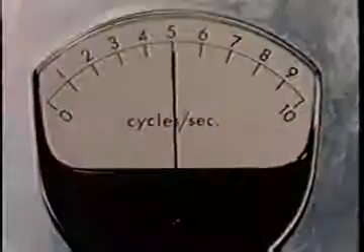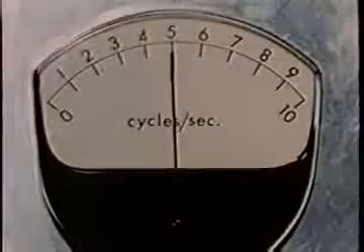In order to find the frequency response of amplification, we put in sinusoidal disturbances which we can control. We start the wave maker oscillating at 5 cycles per second. At 0 airspeed the waves damp as they travel away from the wave maker. With the tunnel running, but below critical airspeed, we don't notice much change in wave damping. As we increase the airspeed and pass critical speed, we see the waves grow.